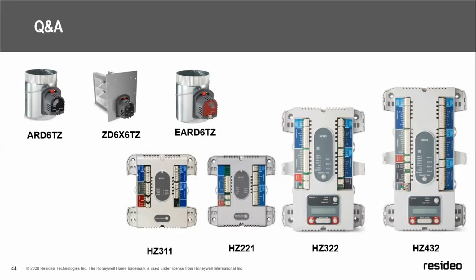Yeah, and when you're using a variable speed motor, you still have to match the bypass to whatever your smallest damper. You still have to bypass the same amount, and the reason for that is startup. When a system starts up, you have to get by the safety of 1.5, and when you get by the safety, it will ramp back down to 1.0. That's the whole purpose of bypass.